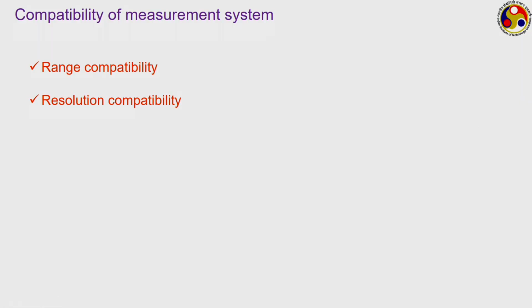Next is the resolution compatibility. If the range is sufficient, then we have to check the resolution. What is the resolution? I am sure you remember, resolution is the smallest possible change in the input required to cause any change in the output.